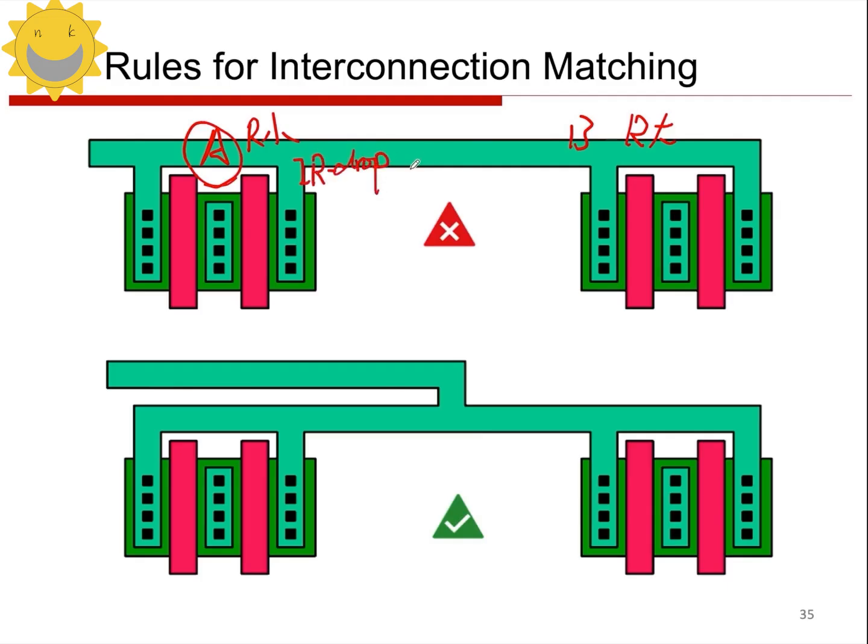What should we do? We should make it smaller, right? And the IR drop suffered by device B is also smaller. So what happens? The voltages obtained by these two devices are different now. The voltage that device A receives is higher, while the voltage that device B receives is lower, because the IR drops are different. So in this case, because of the mismatch in the wires, the voltages are different, and this will lead to an offset, right?